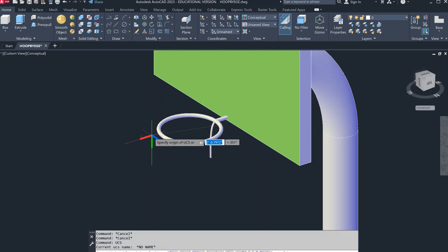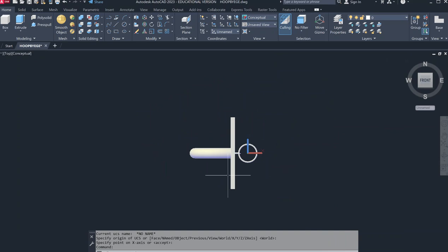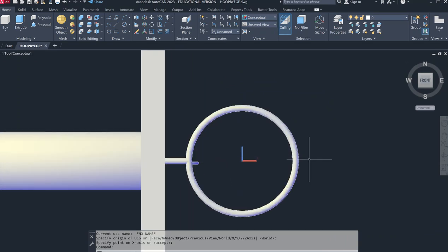However, having done that, I now want to change my UCS. So type UCS, Enter, and the center point. As soon as you pick the center point, put it here, Enter, and look from top down if I can, because I want to use the array command now. Z has to be rotated. So UCS, Enter, X, Enter, rotated, Enter. So Z is now vertical. Why did I set the Z? Because I'm going to use the array command. Array commands always require the Z being perpendicular at the center of the array.